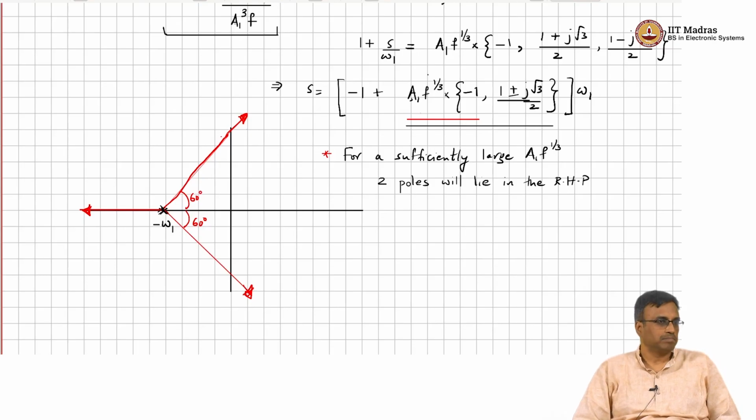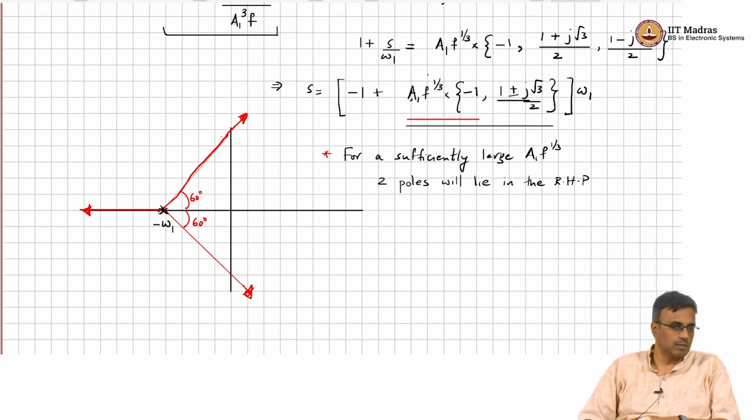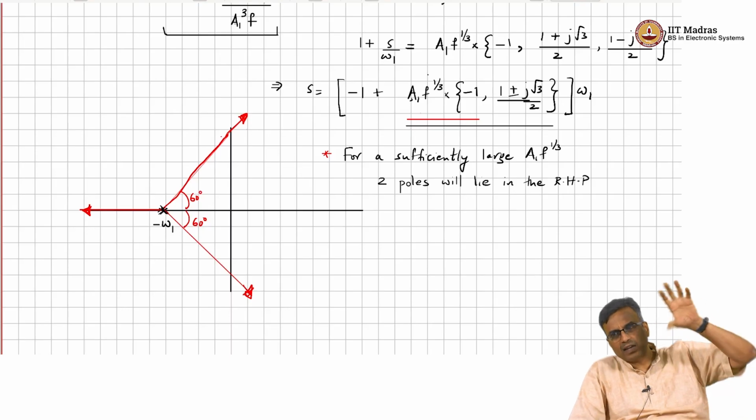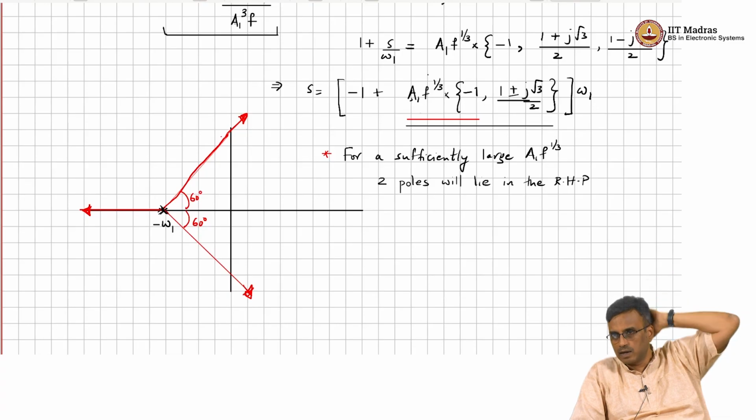They are clear? So now this is bad news because of the closed loop system. The first order system was nice and stable, except that we couldn't get the large loop gain that we wanted at DC. The second order forward amplifier was technically stable, but in practice if you wanted a large loop gain, then you would get a lot of ringing, right.